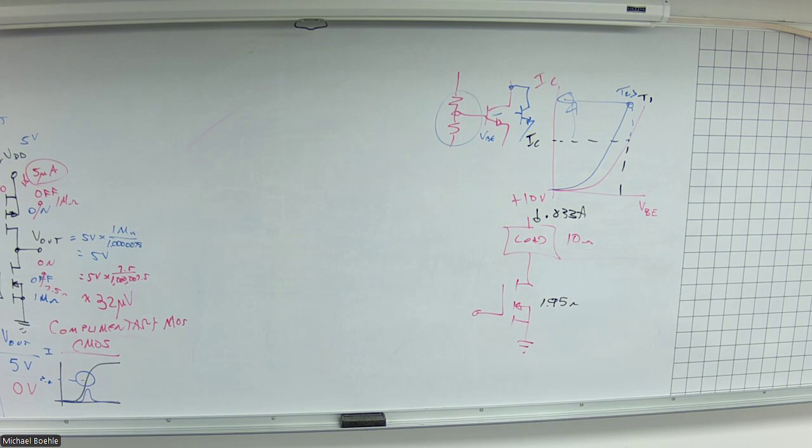But I'm still using it as a switch, right? Remember that was the whole thing about the true sine wave inverter in power supplies, we were turning it on and off so fast that we could make it look like a sine wave. And you have inverters that can do that and provide 10, 20, 50 amps of output. And that's where you're going to see those.